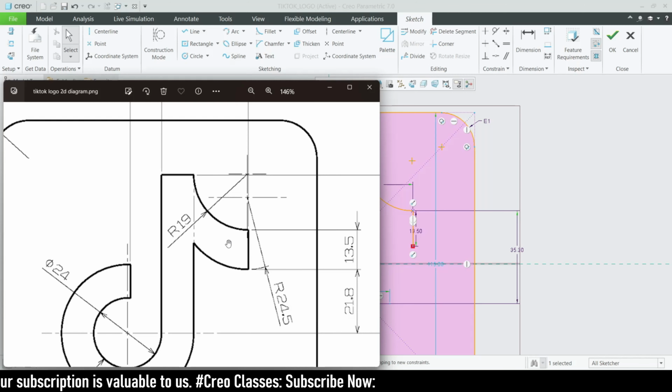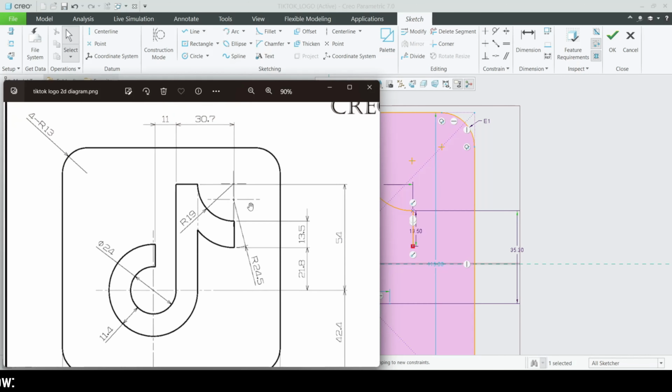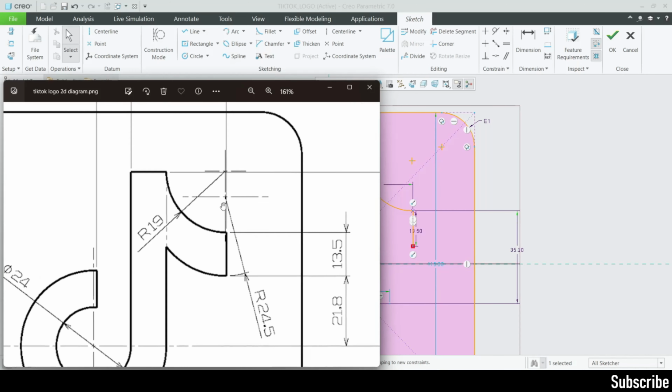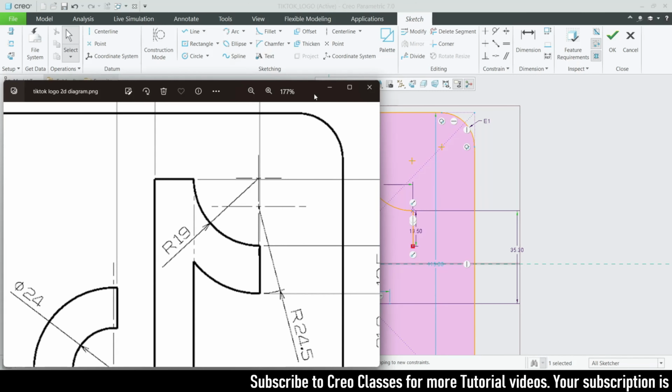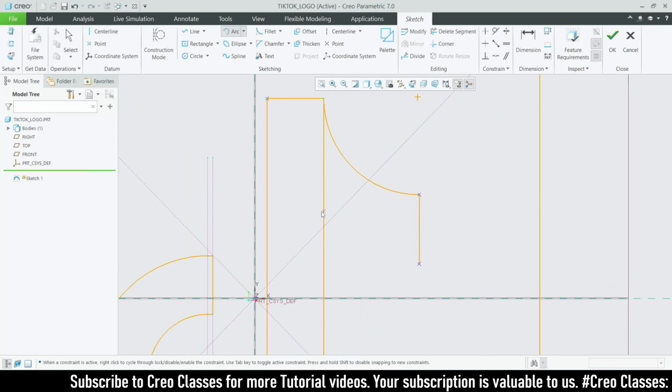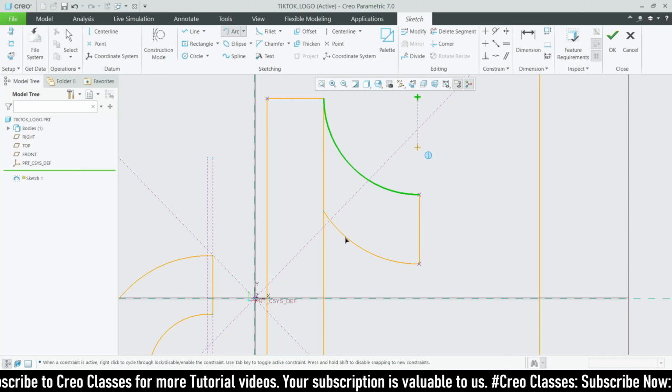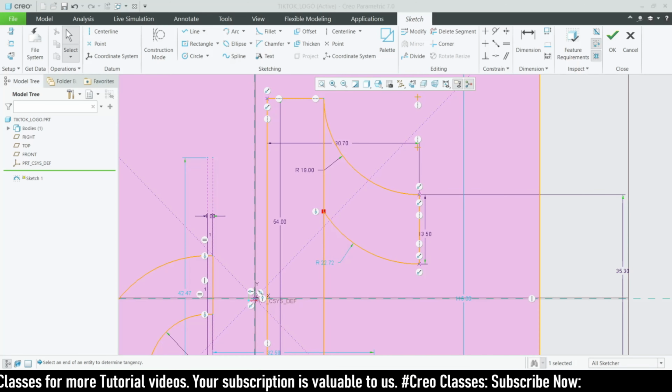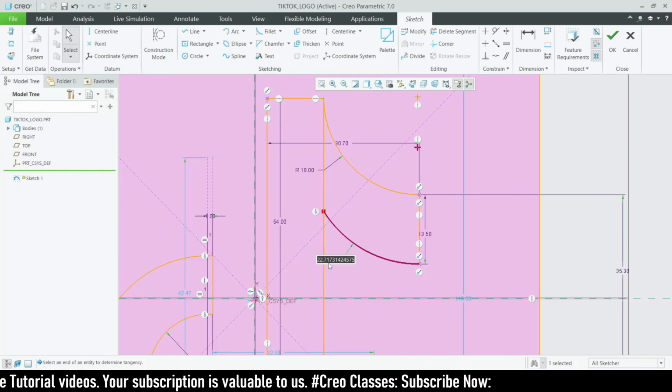These two are the same. Okay, either we can take offset, but if we take offset on this, you guys can see that we can't change the radius value when we take offset of this line. They have mentioned the center point, and for the center point, yeah, it is placing vertically on this, but we need to know about this horizontal axis. Okay, let's try. First of all, I just want to place it like this, and radius will be 24.5.